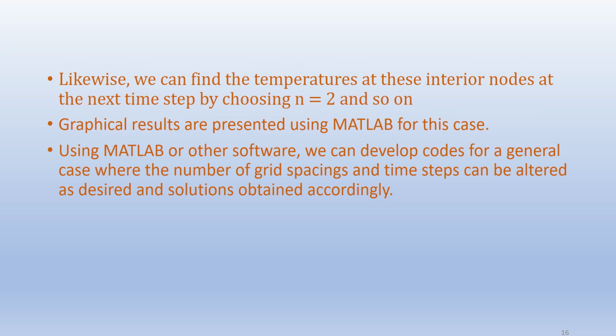Likewise, you can find the temperatures at these interior nodes at the next time step by choosing n equals 2 and so on. Graphical results are presented using MATLAB for this case. Using MATLAB or other software, we can develop codes for a general case where the number of grid spacings and time steps can be altered as desired, and solutions obtained accordingly. We will now go back to MATLAB.